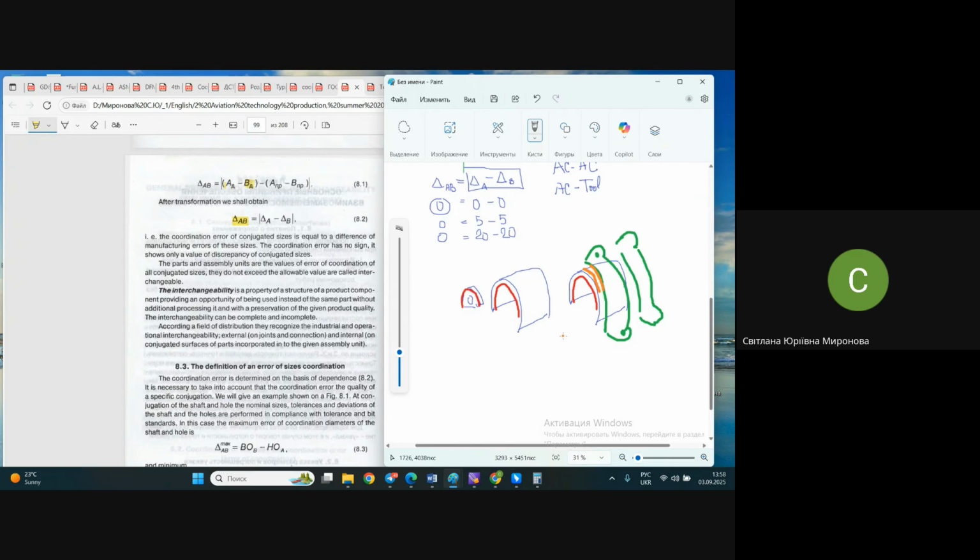And what does assembly component to tooling coordination mean? Tell me please, until I draw the next thing, what do you think determines the shape of the rib and the shape of the skin? Of course, the rib was produced on a foam block forming die, and the skin was produced, let it be by stretching or some bending punch.